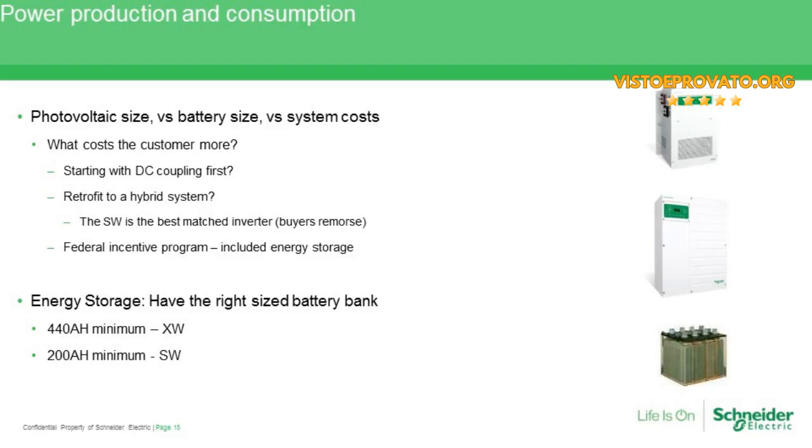So with battery efficiencies removed out of the equation, DC coupling becomes a little more palatable, if you will. And this is assuming, of course, that we're in a cycling application. And with AC coupling, this is assuming that we're using the efficiency of the grid tie inverter when the sun is shining. So as little as 4%. With a grid tie inverter and the wiring losses in there, that's where we get that 4%.